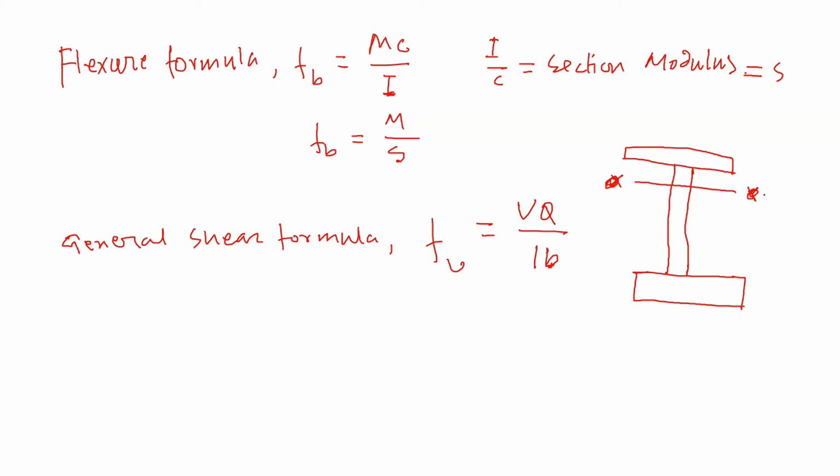XX is used as the neutral axis, and maybe Z is used for another thing, so let's use M1, M2 as the plane that we are interested in to calculate the shear stress. What is oftentimes done by mistake is calculating the Q, the area moment.